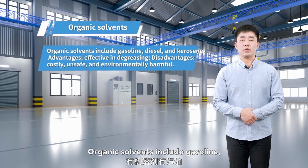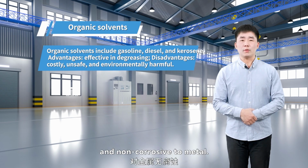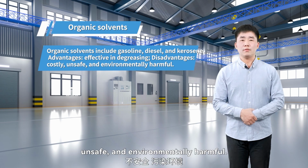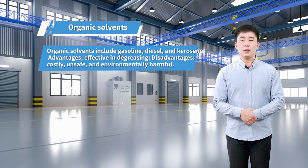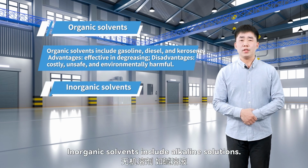Organic solvents include gasoline, diesel, and kerosene. Oil washing is convenient and effective in degreasing and non-corrosive to metal. However, oil-based cleaners are costly, unsafe, and environmentally harmful. With growing energy concerns, their use has been limited. Inorganic solvents include alkaline solutions.